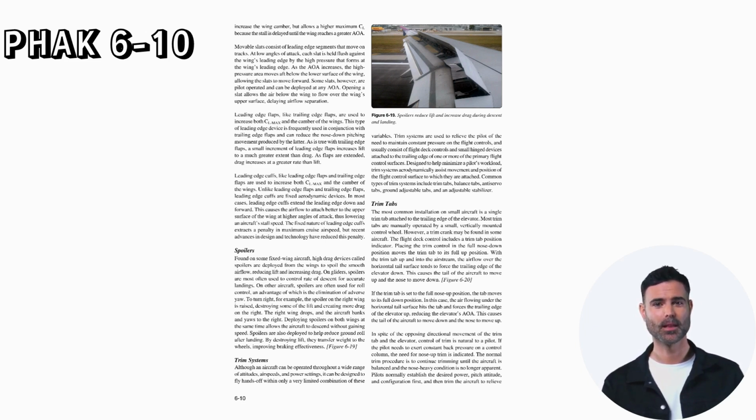Leading edge cuffs, like leading edge flaps and trailing edge flaps, are used to increase both CL max and the camber of the wings. Unlike leading edge flaps and trailing edge flaps, leading edge cuffs are fixed aerodynamic devices. In most cases, leading edge cuffs extend the leading edge down and forward. This causes the airflow to attach better to the upper surface of the wing at higher angles of attack, thus lowering an aircraft's stall speed. The fixed nature of leading edge cuffs extracts a penalty in maximum cruise airspeed, but recent advances in design and technology have reduced this penalty.